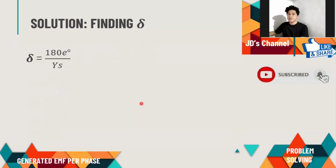And then finding the delta, we have the formula 180 electrical degrees over the YS we got earlier. So delta is equal to 180 electrical degrees over 6, and the answer is delta equals 30 electrical degrees.